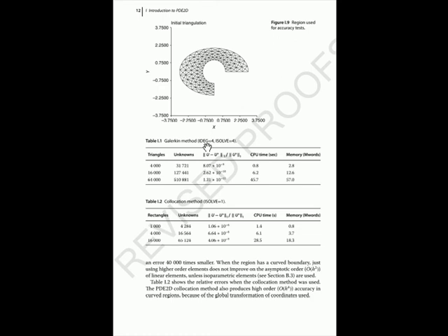So that's much better than finite differences, which is order h squared normally, and not even that if you have a non-uniform grid. But PD2D for a general curved region, like this problem here, is using the Galerkin method. It's got a curved boundary. The inner boundary is a circle, the outer boundary is an ellipse. And using fourth order elements, you get h to the fifth accuracy, where h is the diameter of the average triangle. And you can see the error is extremely small here.